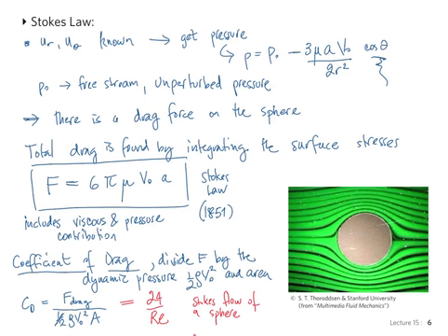Or you want to calculate how much residence time you require for an industrial application where you want to settle all of the dirt in water for cleaning up the water. So first you want to settle the dirt, and then you want to take out all the clean water from the top to take it to some sort of disinfection stage afterwards.